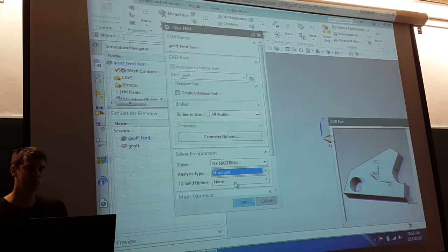Often, in that situation, the mesh you apply to one particular region of a part isn't necessarily the same mesh that you want to apply to another part. So that's what these mesh collectors are. They basically associate mesh characteristics together and allow you to apply those characteristics at a later stage as you work through the model.